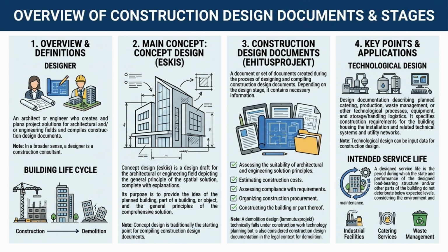Finally, every building has two important time-related concepts: building life cycle and intended service life. The building life cycle refers to the period from construction to demolition. Intended service life, or design working life, is the intended duration during which the load-bearing structure or other parts of the building are expected to maintain their condition and performance, taking into account the environment and required maintenance.